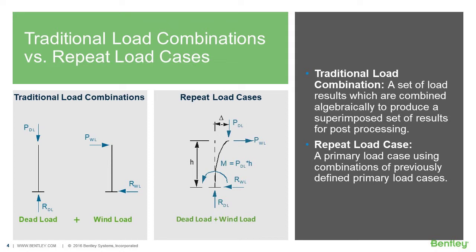If your analysis includes things like tension or compression only members, or any second order effects such as P large delta or P small delta, you're going to want to make sure that you are generating repeat style load cases, because those load cases will be combined together, and then their combined results will be determined by the program and available. And of course, as we know with P delta, you can experience some additional moments due to those loads being added on the structure simultaneously.